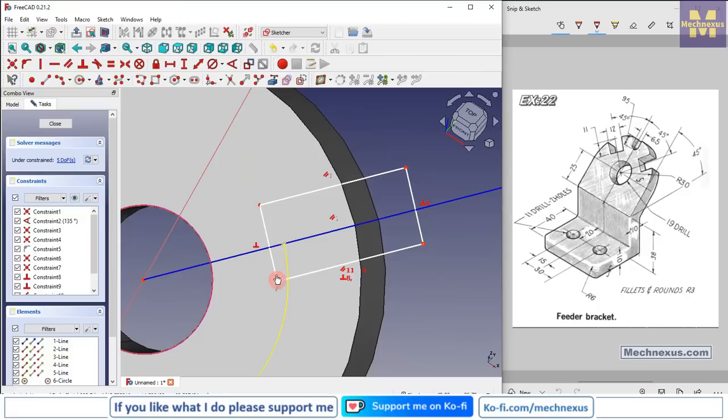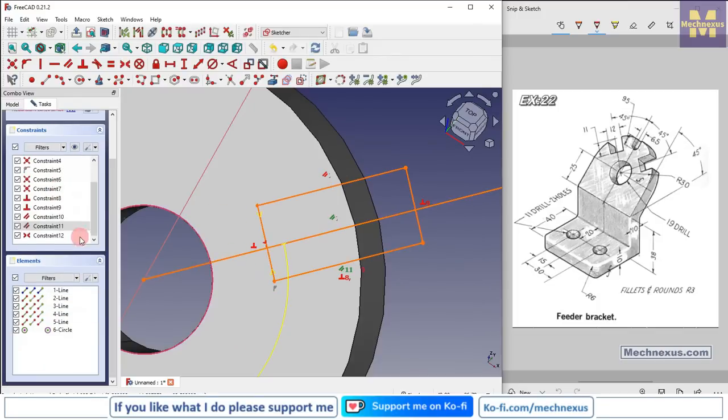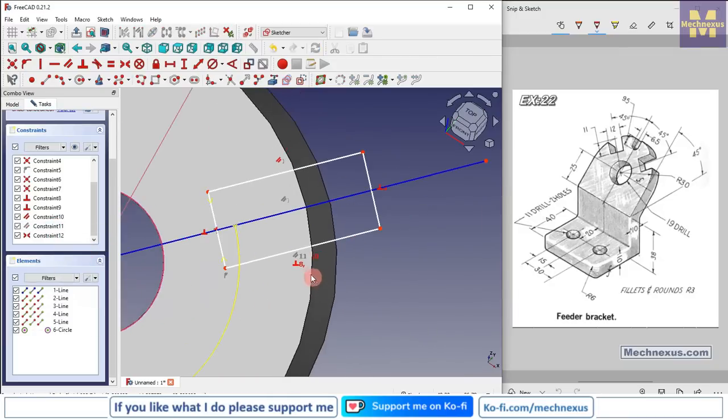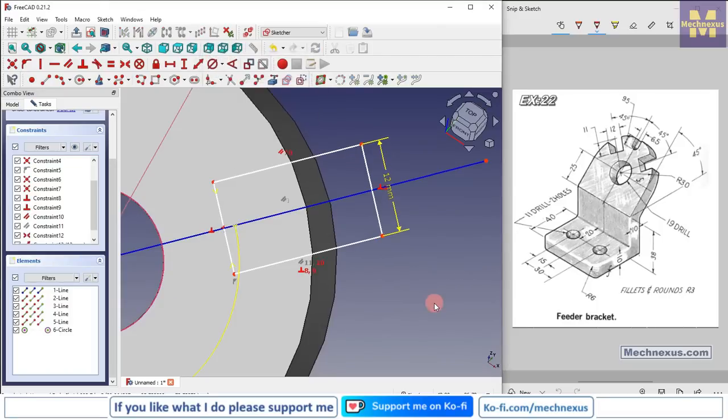And now here we will make these 2 points symmetric with this construction line. So we will use the symmetricity, select this point and this axis, and we will go here and deactivate the conflict. And now we will select this line and provide the dimension of 12 mm,